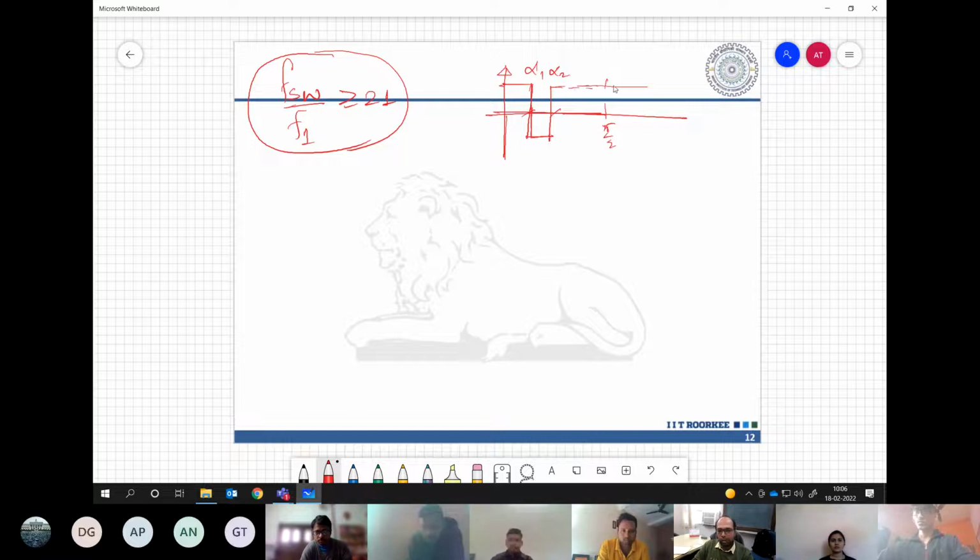So one thing you note over here is that if let us say I asked you to generate modulation index say for 0.8. So we are asked to generate output, of course, balanced three-phase output. For this particular modulation index, we need to know the switching angles at least in all the, within one quarter cycle, all the switching angles within this.